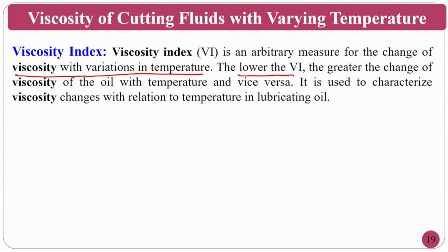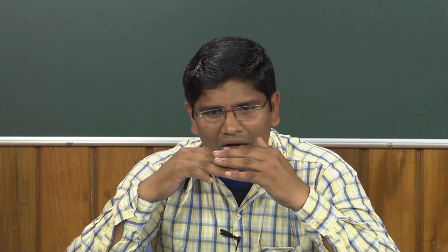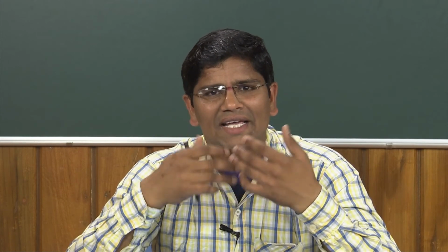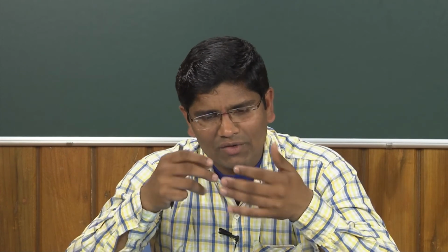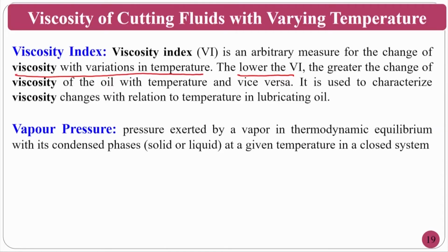Why I want to introduce this term is, if the viscosity index is higher, that means it won't change much in viscosity at higher temperatures also. If the viscosity index is lower, what will happen? The fluid will change its viscosity with respect to temperature. We will describe the next one, that is called vapor pressure.